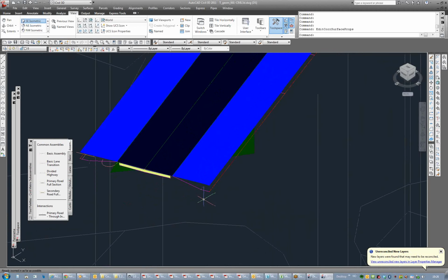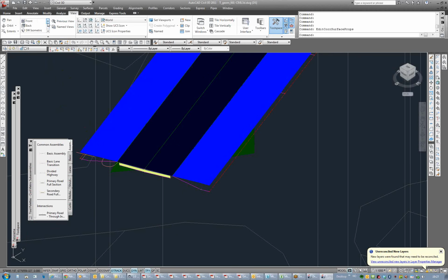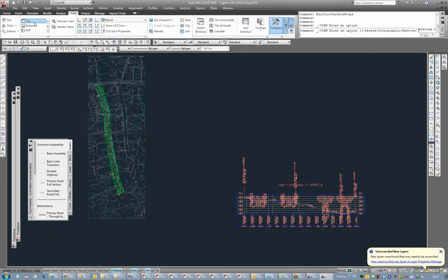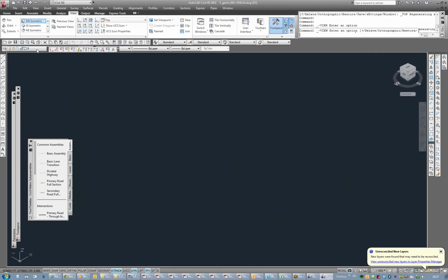Okay, so that's showing the difference between the existing. Yeah. I've got to rotate that. How do I do that? We've got to go back over here. Yeah, just re-rotate. You can go to southeast or top or whatever, because the solids won't show up until you go to an isometric.